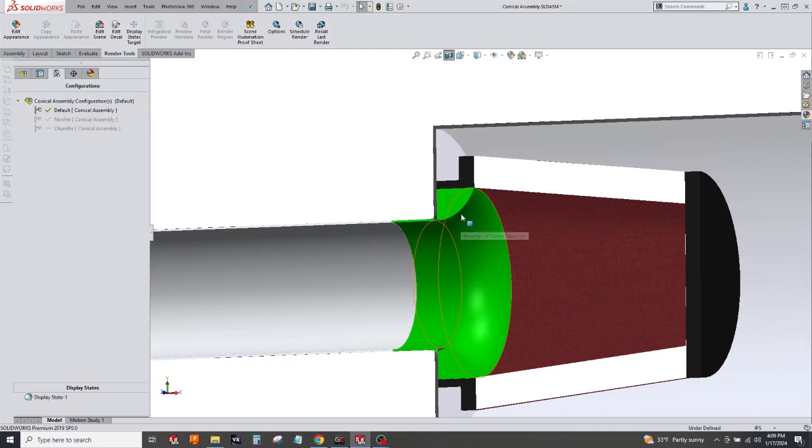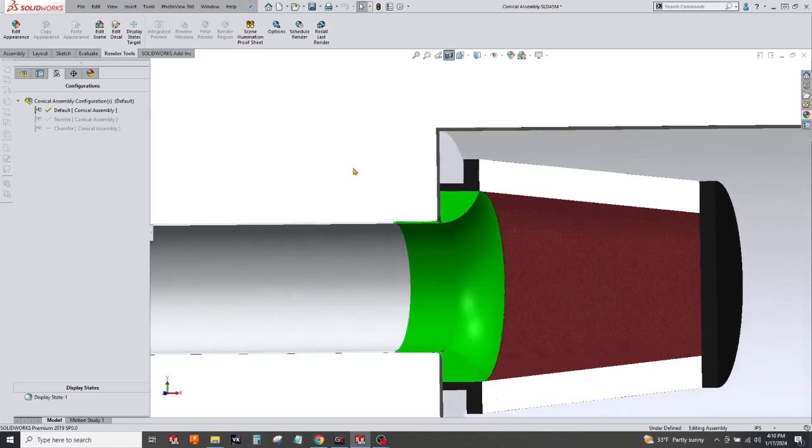And what this does is applies a fillet to this geometry. This is going to serve as our velocity stack. And so what is a velocity stack? It's a really fancy term for fancy fillet. There's a ton of literature out there you can research on what is the best geometry and how to optimize it and get the most flow that you possibly can. But for all intents and purposes, it's a fancy fillet.